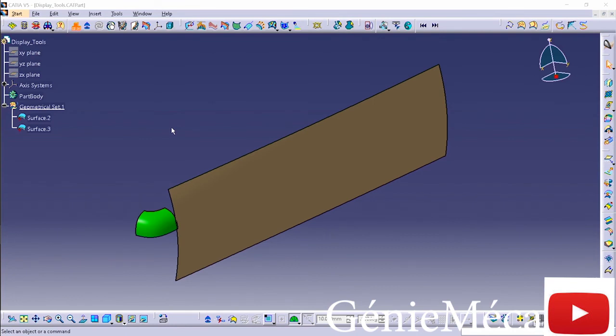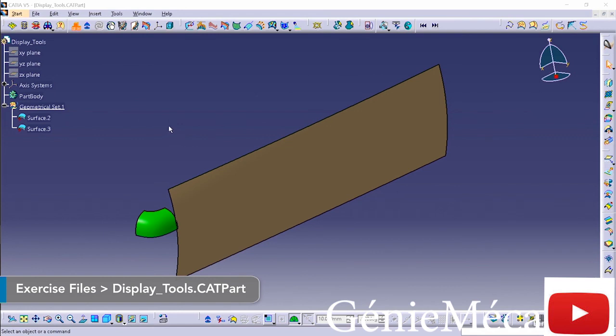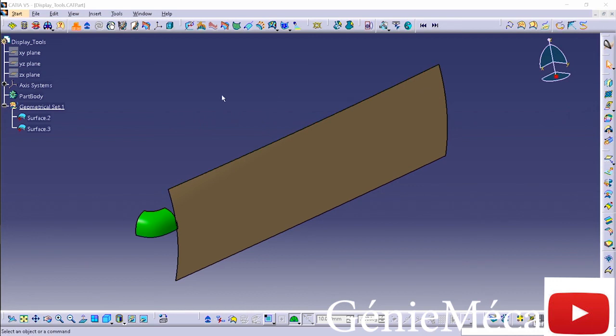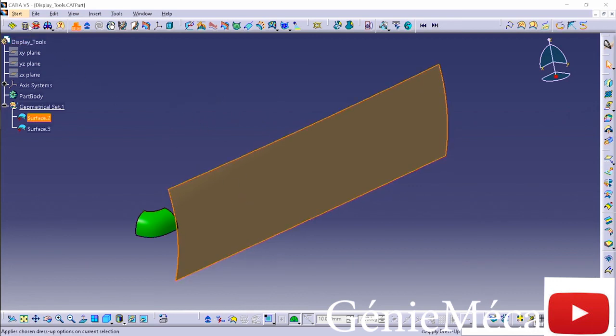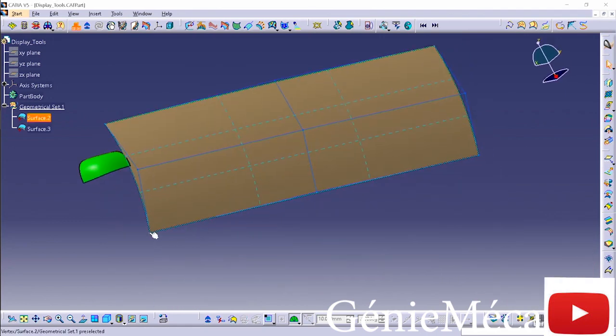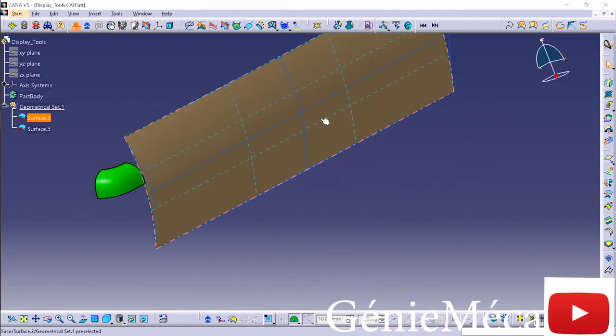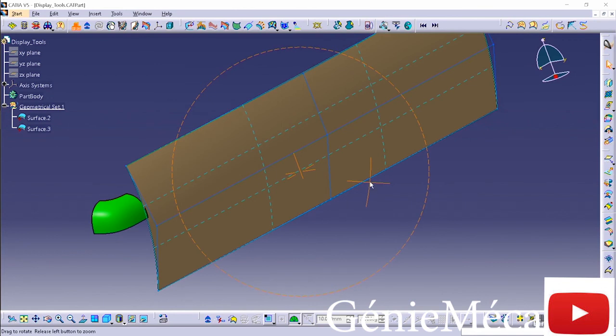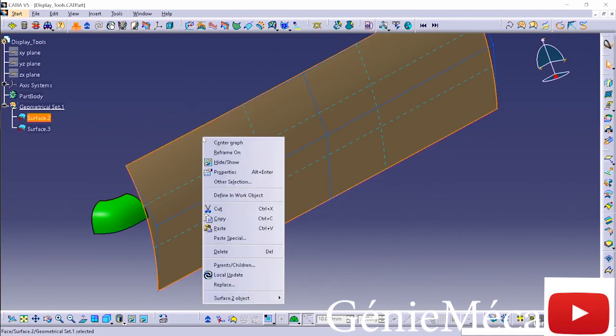As you're working with your curves and surfaces, you want to make sure that they look good. One great way to do that is to visualize the control points. Now, the control points that we use here for manipulating the surface can be displayed using a tool called Apply Dress Up. I can show control points and segmentation. I'll turn both of those on, select OK, and as we can see, I have my control points displayed in this blue frame. These dashed lines that you see are just isoparms across the surface. Go ahead and hide that.